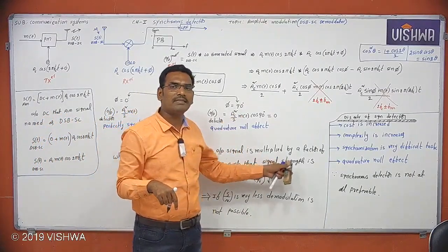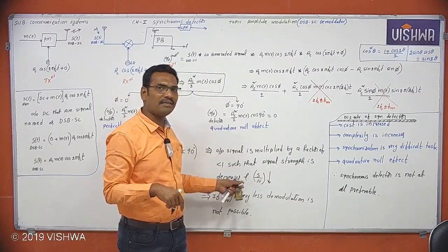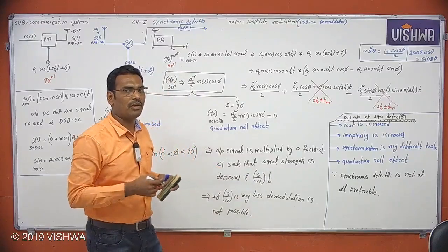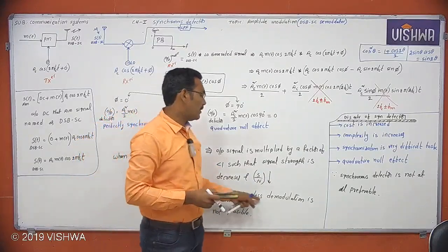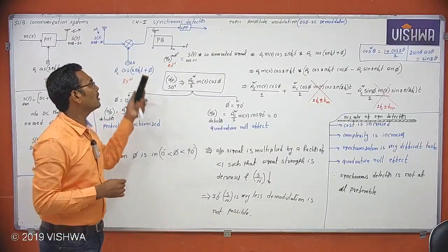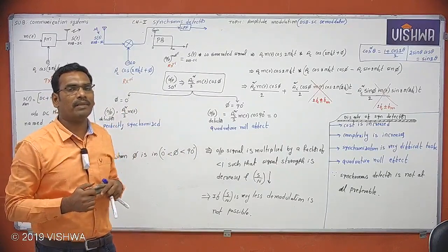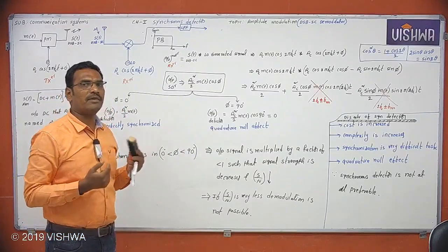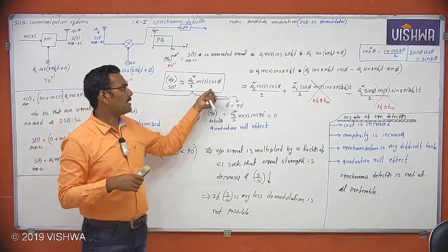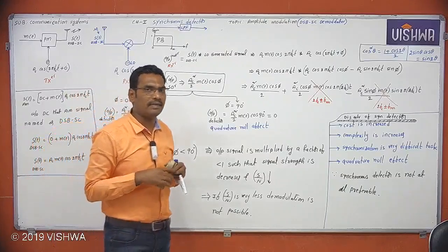When the signal strength decreases, the distortion will increase, and the effect of noise will be more. When noise is dominating, the signal to noise ratio decreases, and then demodulation is not possible. Then what is the use of increasing the cost and complexity? All these things are not working. When demodulation itself is not possible, synchronization by using a local oscillator, providing the cos phi phase, and extra hardware required to nullify that phase is a very difficult task. It is not an easy task.